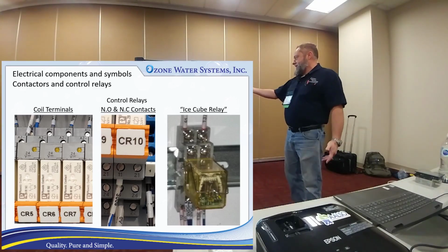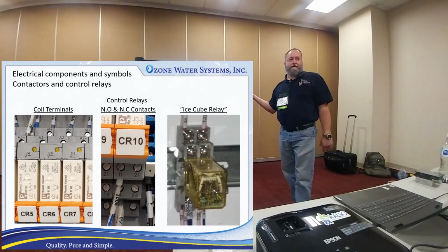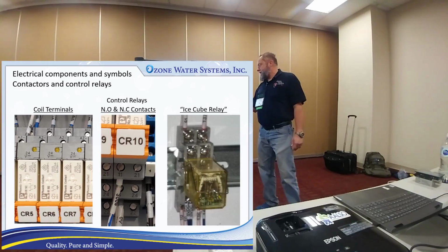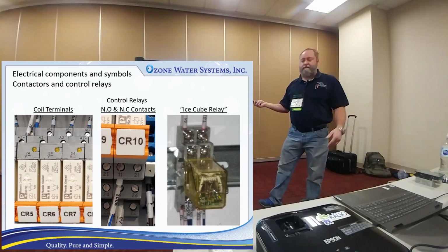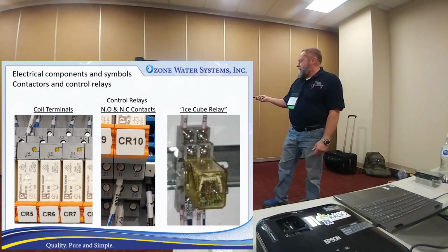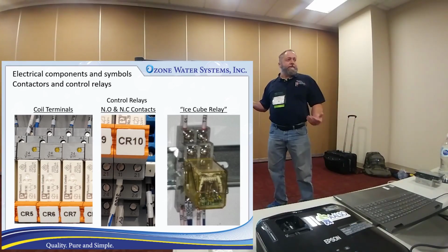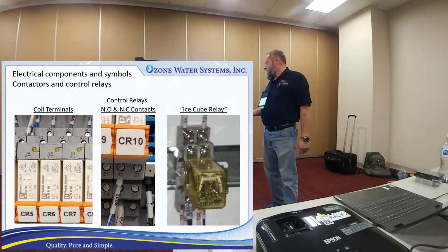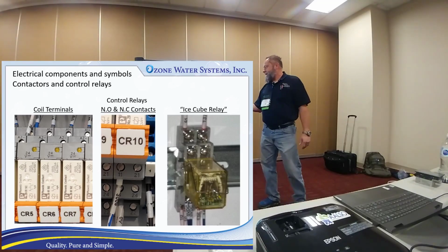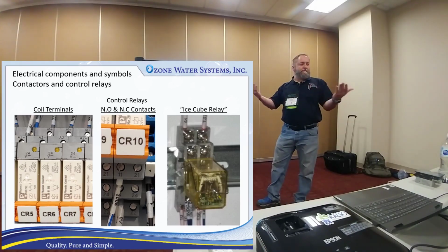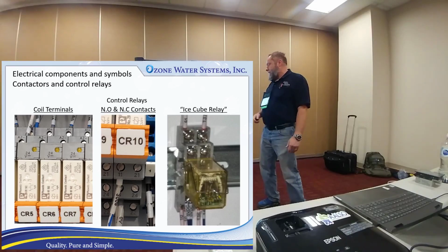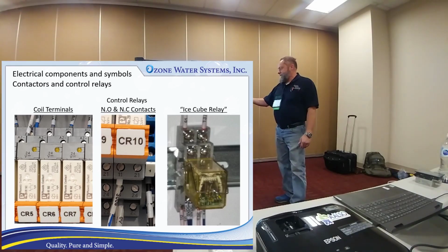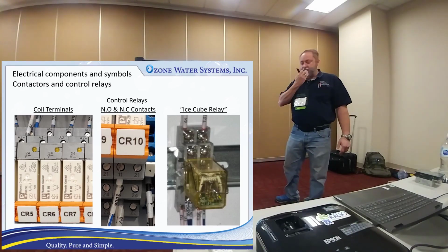And again, these take literally microamps or milliamps to engage these relays, but they can handle up to 10 amps or so. And obviously with any relay or any part, there's a huge range of capacities and power. There are a lot of relays between here and the big contactors to give you different power ratings for control relays as well. But these are the ones you're going to see most of the time in most of these panels.